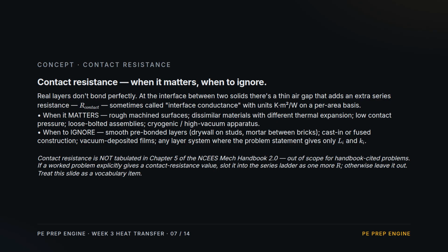Contact resistance. Real layers don't bond perfectly. A thin air gap at the interface adds a series resistance, sometimes called interface conductance. It matters for rough machined surfaces, dissimilar materials with different thermal expansion, low contact pressure, loose bolted assemblies, cryogenic apparatus.